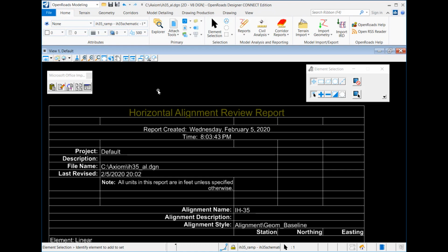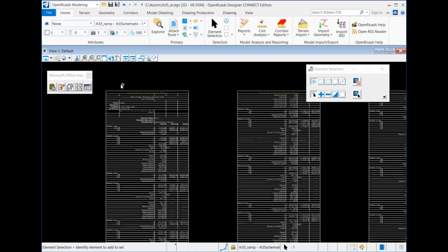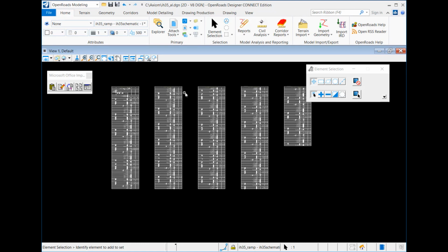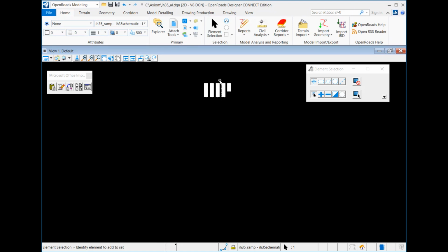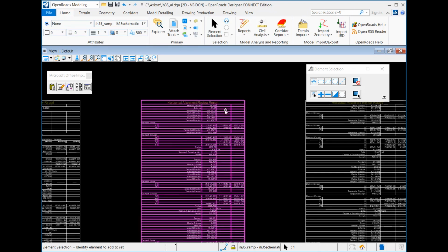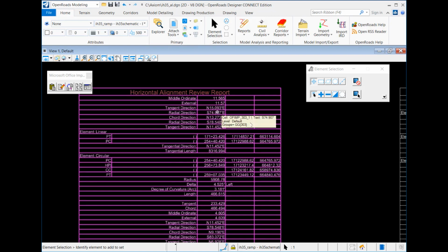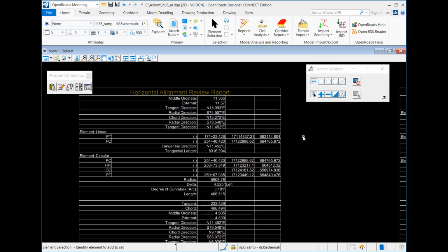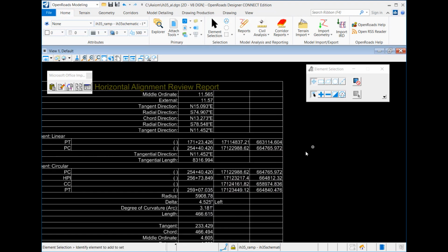We'll eventually come back, of course, and put this data inside a plan sheet, but for me as a designer, I want to be able to see this data quickly and know that this data is stored both in the spreadsheet and with a link back to the DGN file. Now that link is a live link, so the Office importer remembered that, and I have the ability to edit that source data. So this button will open up Excel and let me edit that source data.